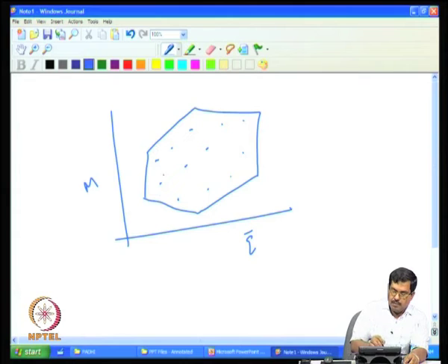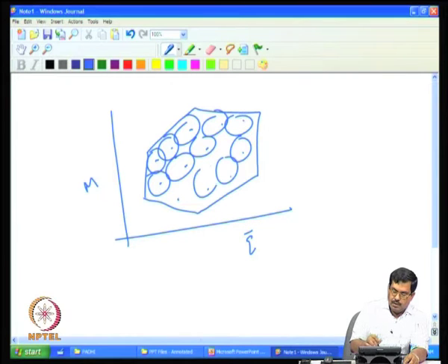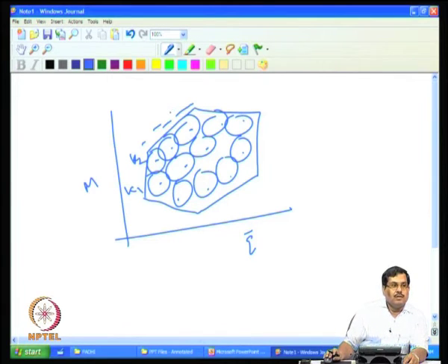About each of the operating points you linearize, and linearization is locally valid, we know that. So, in the local neighborhood you design different gains. In other words, let us say for this one this will be K1, for this K2, and things like that. So, everywhere you design local linear controls based on local linear plants. And then you stitch them up using some sort of an interpolation routine.